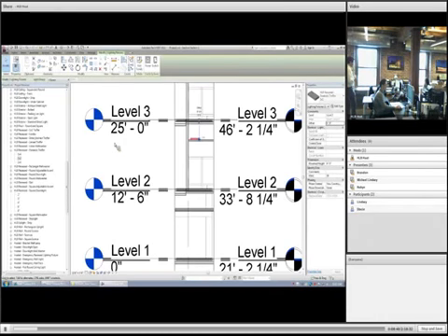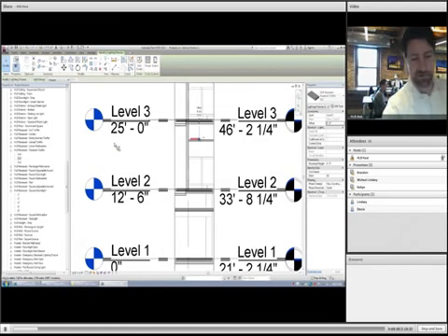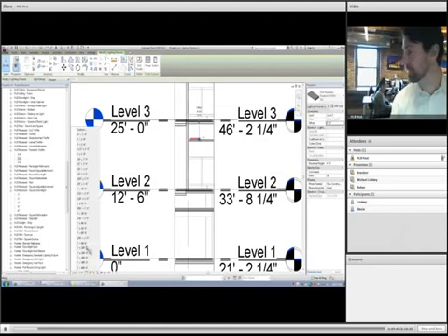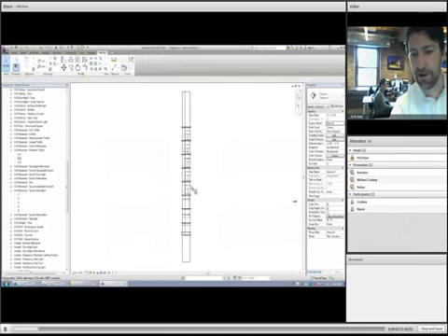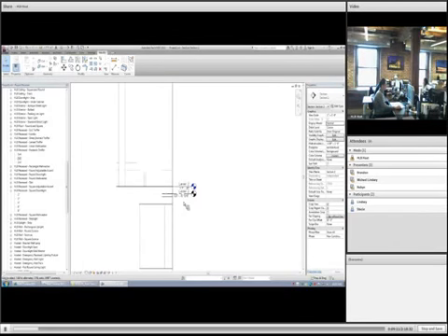Oh, okay, great. Now, one thing too, after I made those interior elevations, I know sometimes the scale is really, really hard to see on these levels. Look at this. If you're just in a working view, this is the virtue of having working views: change that scale to something more sensible so that the level heads aren't in the way. It's one of the more annoying things. You'll just need to scale it down because it's a working view. It's never ending up on a sheet, right? So you can do anything you want to do in here.